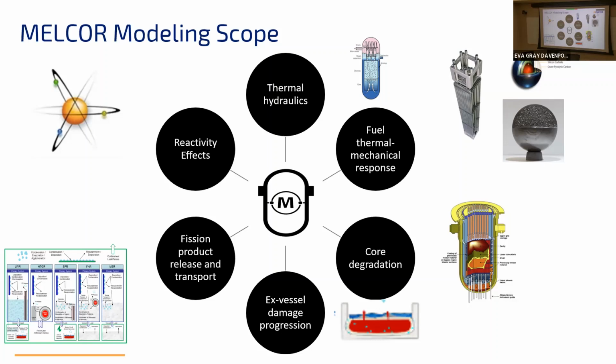And so MelCore, and this is a simplification, has really evolved generically. It's got a general thermal hydraulics model that can capture not just light water, it can capture helium, it can capture molten salt thermal hydraulics, it can capture sodium thermal hydraulics. And if you've got another fluid with a well-defined equation of state, we can plug that in. It captures the fuel thermal mechanical response, not just for light water reactors, but also for high temperature gas reactors, for TRISO. We're moving into sodium fast reactors this year and metal fuels.